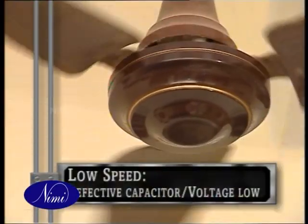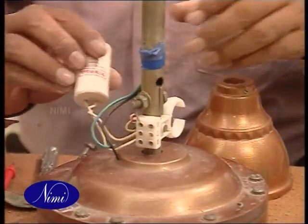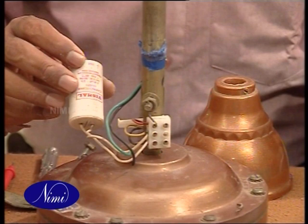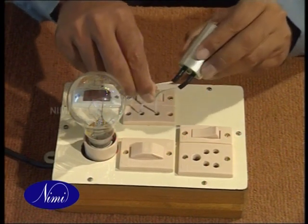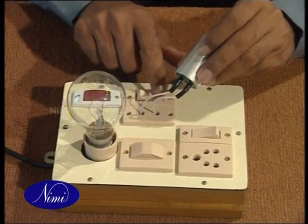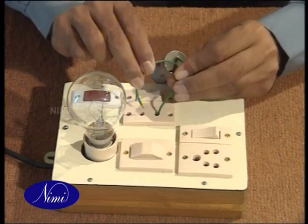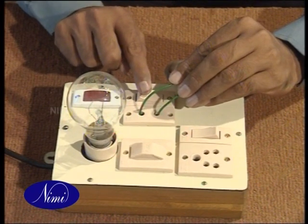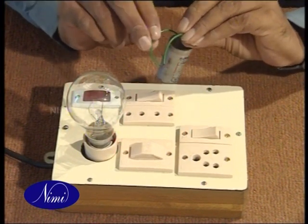Low speed might be due to a defective capacitor and low voltage. If the voltage on checking is found to be normal, remove and test the capacitor. A leaky capacitor cannot be tested easily while connecting in the circuit. To check whether a capacitor is open, connect it to the test lamp in series. If the lamp glows dimly, it means the capacitor is okay. If the test lamp does not glow, then the capacitor is open. If found defective, replace the capacitor with another one of the same capacity.